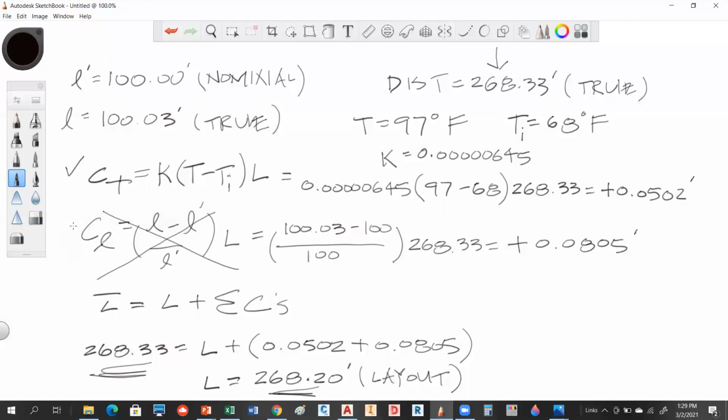Yeah. There is a temperature thing going on there, okay? What's happening is temperature affects your column of air that you're shooting your carrier beam through. And what that does, you can think of air like a fluid as far as your EDM is concerned. So if you're shooting a bullet through molasses or through water, there's going to be a difference. It's going to slow the velocity down of that bullet, right?